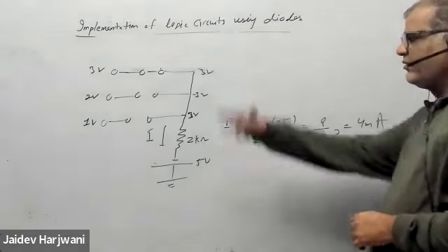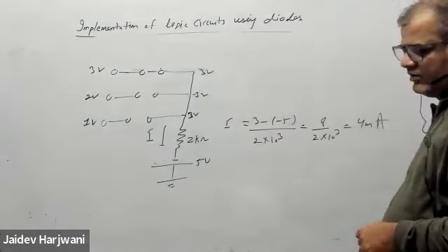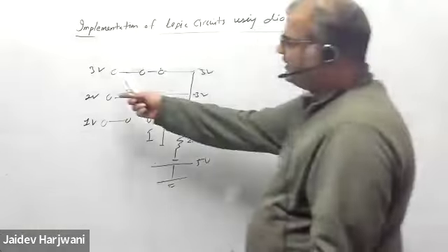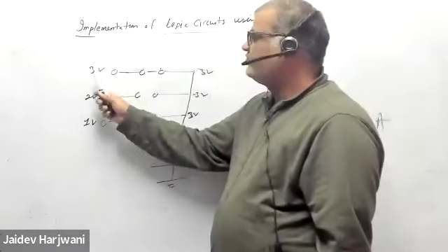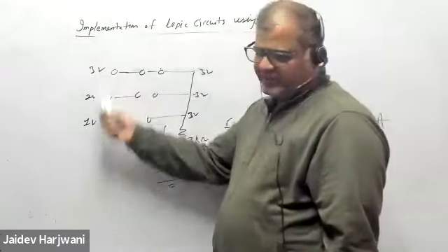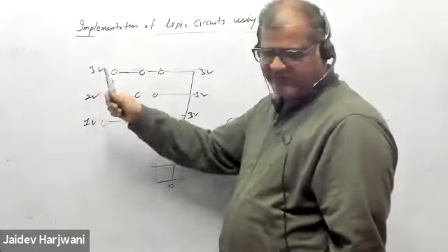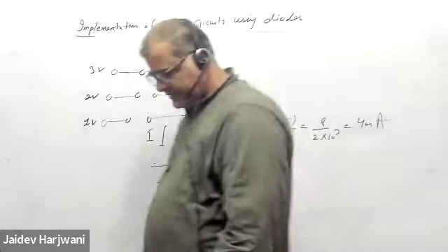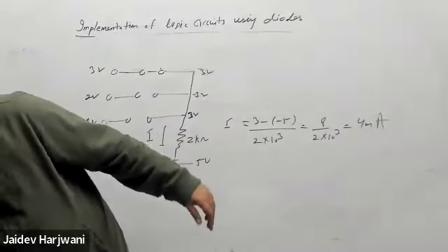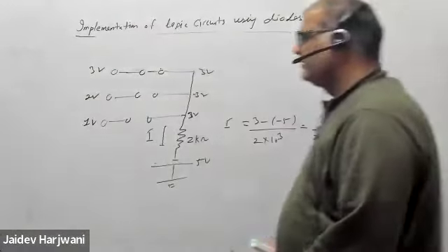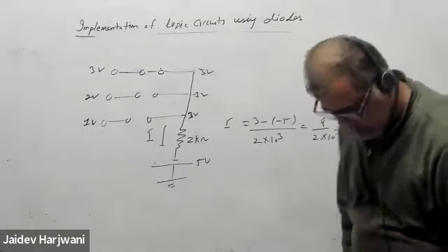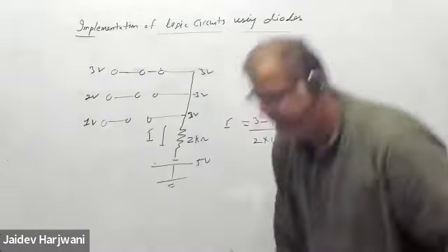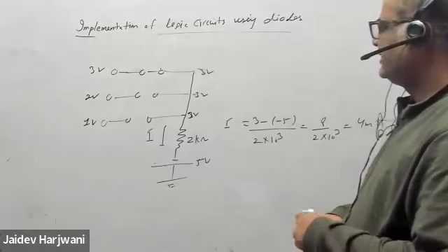So whenever diodes are conducting this way, always the higher will conduct. And if you are applying 0, same voltage, so whatever you are applying, suppose you are applying 5, it will come to this. This is basically your OR gate. This is a 3 variable OR gate. Now let us take the AND gate.